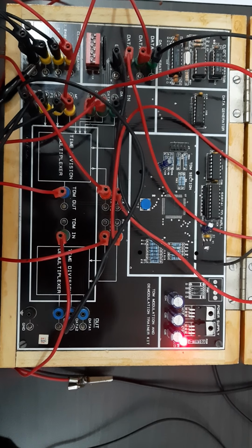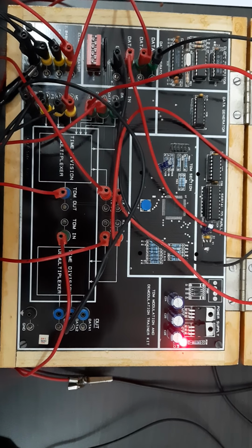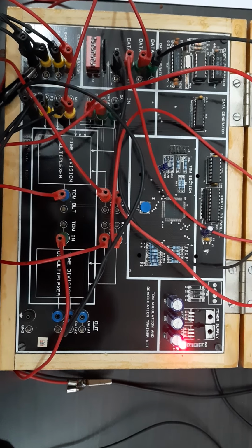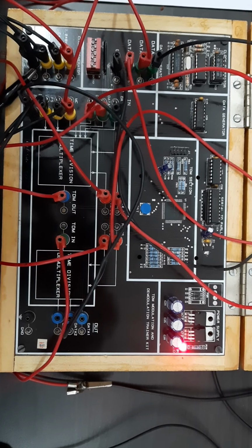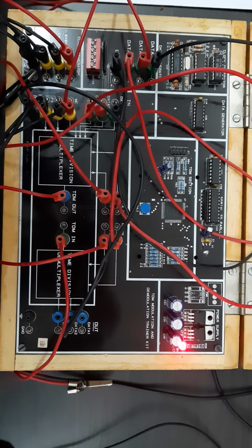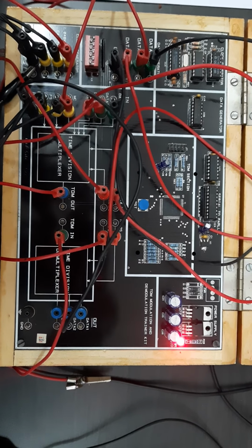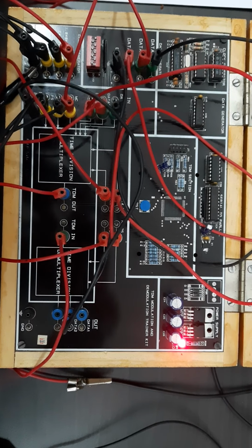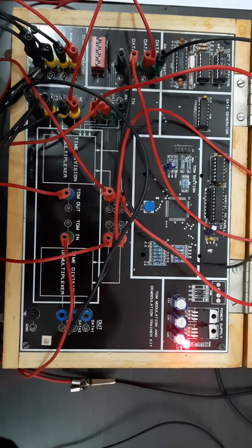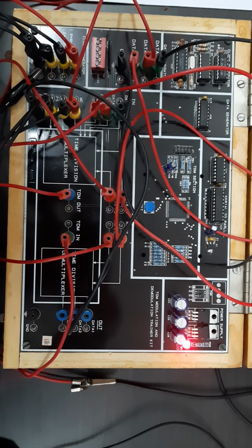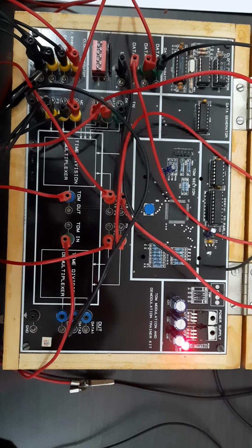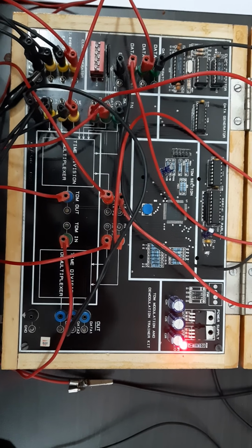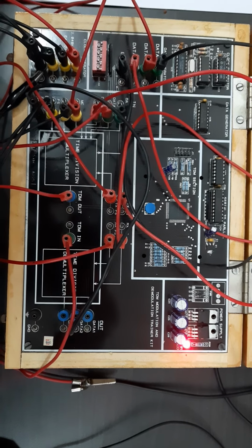The time domain is divided into several recurrent time slots of fixed length, one for each sub-channel. A sample, byte or data block of sub-channel 1 is transmitted during time slot 1, sub-channel 2 during time slot 2, and so on. One TDM frame consists of one time slot per sub-channel. After the last sub-channel, the cycle starts all over again with a new frame, starting with the second sample or byte of data block from sub-channel 1, etc. So in a single channel many data frames are transferred with this technique.